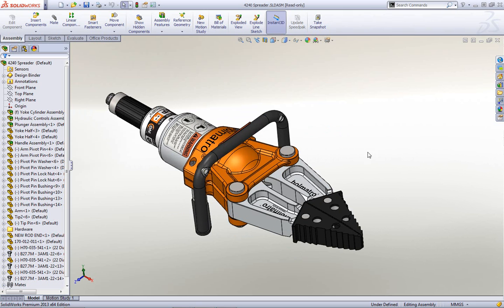I think everybody's familiar with this assembly, or at least has heard of it. Okay, so I want to point out here that this file is read-only. This is one layer of control, meaning that I can look at assemblies that are inside the vault. I can even manipulate them. However, I'm not going to affect anything that's there, any release documentation, until I put it into a state that I can write to this file. So what-if scenarios or things like that, I can perform.